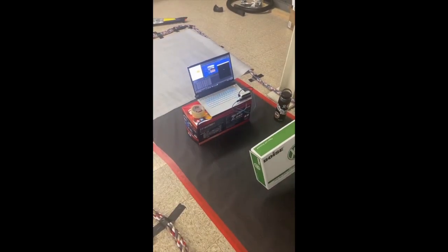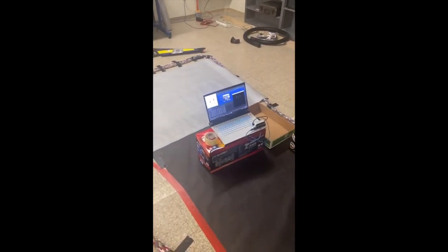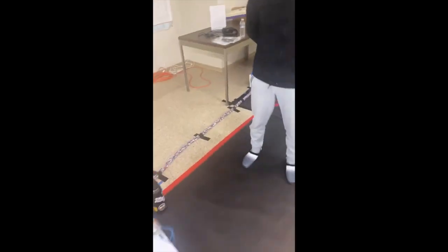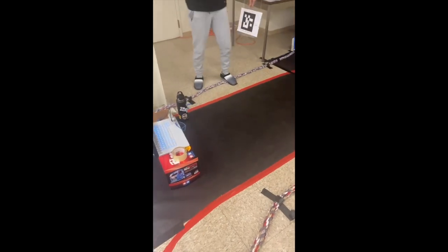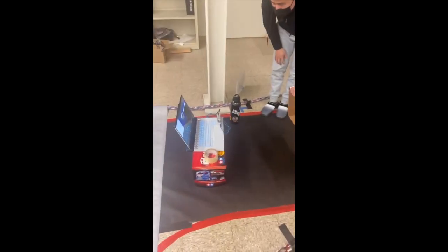We've also tested the D435i depth camera's performance in building an occupancy map from a depth map in the real world. As you can see in the video, the performance is also pretty good. We can clearly see that each frame reflects the obstacle, and the black surface turns out to be not a deal breaker for the camera. But what we found is that we do need to increase the frame rate of the obstacle detection and point cloud conversion algorithm.